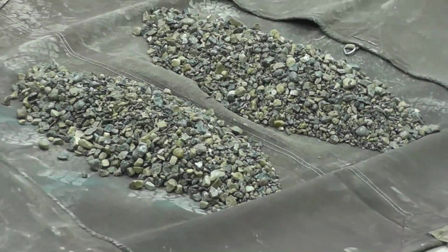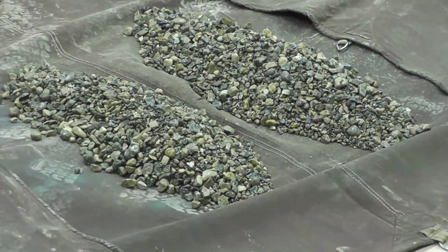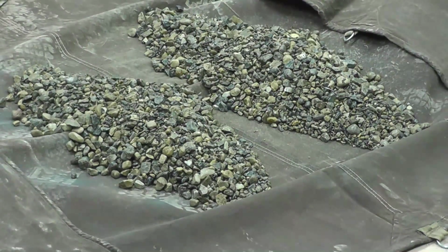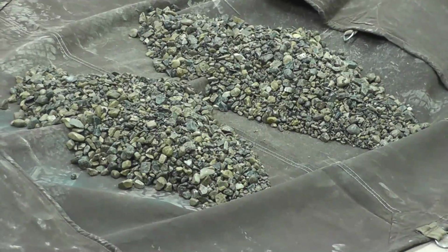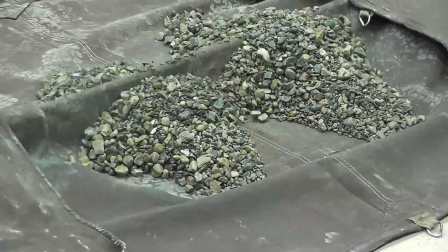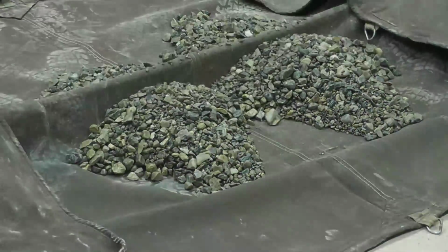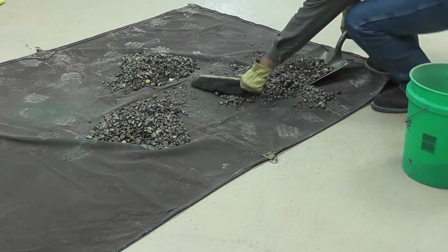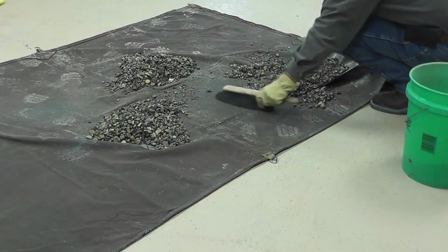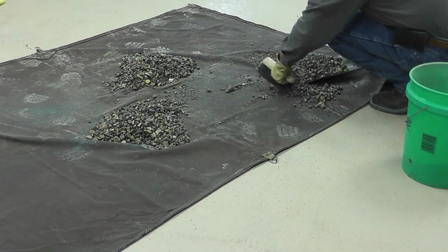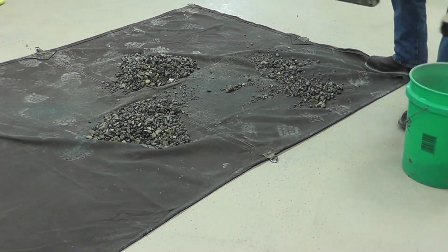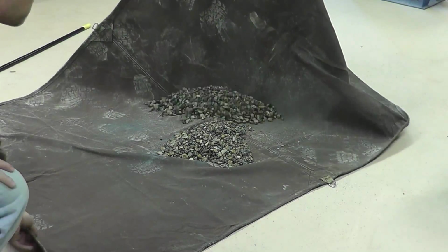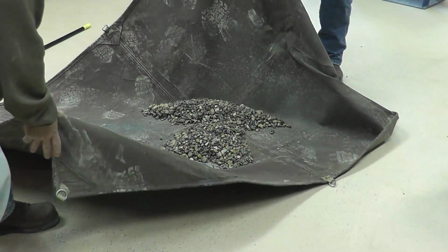Slide the stick under the canvas blanket again at a right angle to the first division and dissecting the 2 halves of the sample through their centers. Lift the stick evenly from both ends, dividing the sample into equal quarters. Remove 2 diagonal parts, including the fine material, and clean the area. Successively mix and quarter the remaining material until the desired sample size is obtained.